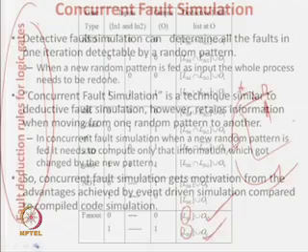Now, what happens? Once you have that, given a circuit, you apply a random pattern, then our goal here is that you have to traverse the circuit once, and in that one traversal of the circuit, you have to find out what are the faults that are detectable. So, here are some rules we are applying: if there is an inverter, what are the rules; if an AND gate, what are the rules; if there is an OR gate, what are the rules. By applying the rules from level 0 to level 1 to level 2, level 3 and so on for the circuit, you go to the output, and easily you can find out the list of all faults which are detectable by that input, and that is done in one scan of the circuit. Now, say there are 30 faults in the circuit, then in one scan of your circuit you find out that some 20 faults have been detected.